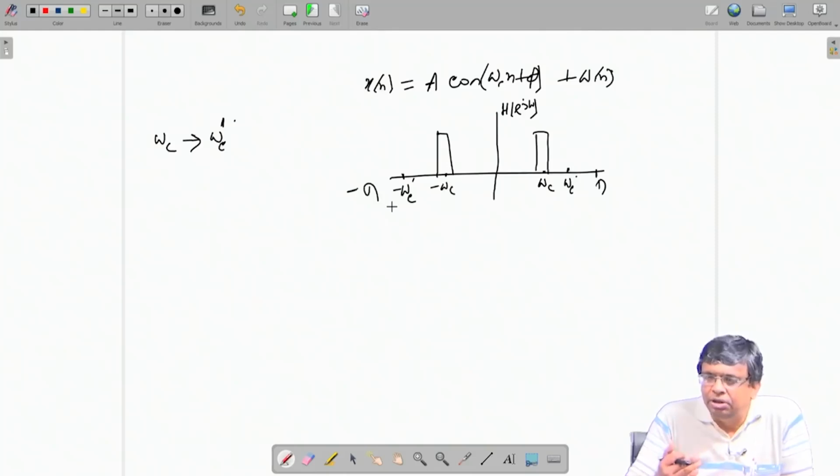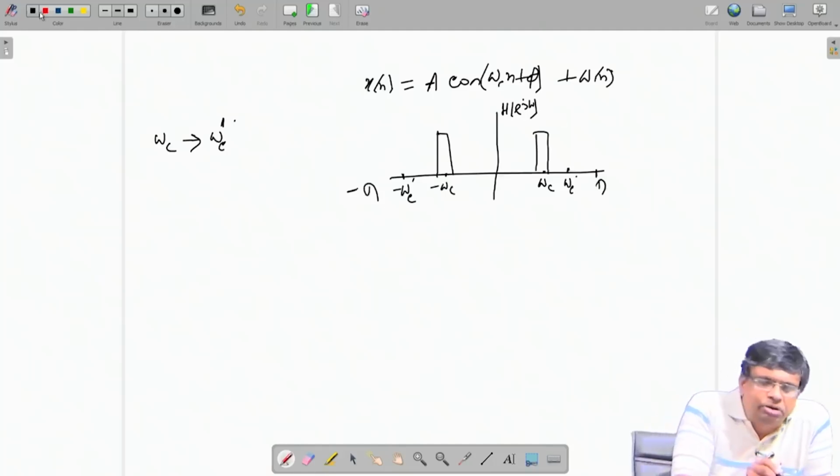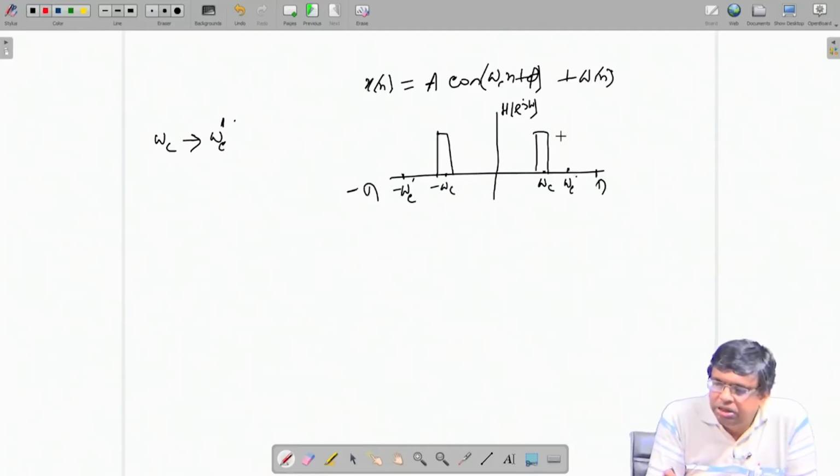Can I make it self adjusting, so that by looking at the input signal and doing some calculation, it can identify what the desired response should be, and change the filter coefficients, maybe in an iterative manner, so that eventually this filter becomes a new band pass filter?